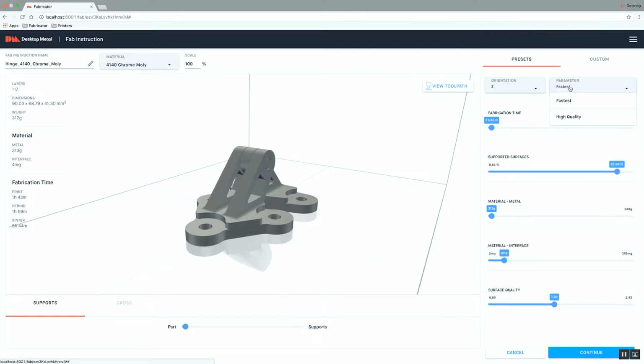In addition to that, you can specify the parameters. You know, what should the extrusion rate of the material be? How fast is the velocity of the head? What's the temperature of the nozzle? And what we've done is we've pre-configured two different parameter sets, one with a thick layer thickness and one with a thin one. So it can either print quickly or print with a better surface resolution. Now, an expert will know what combination of orientation and parameter file they want to accomplish a certain thing.